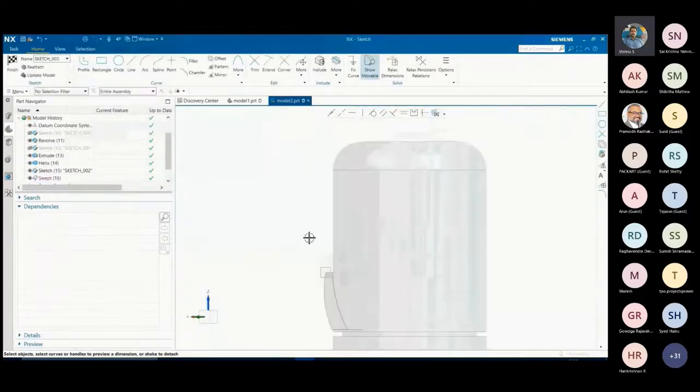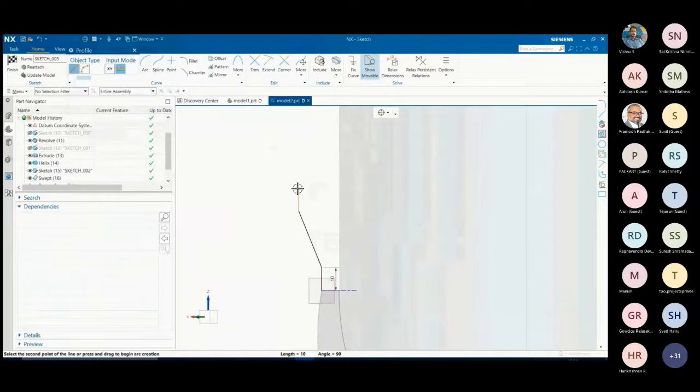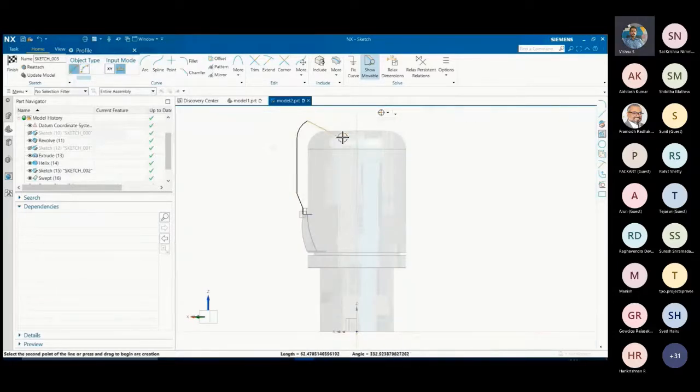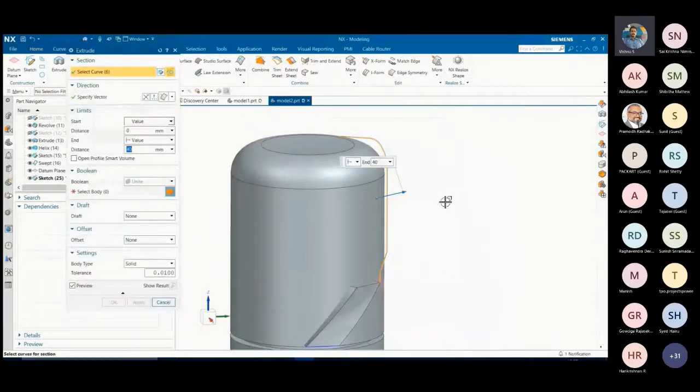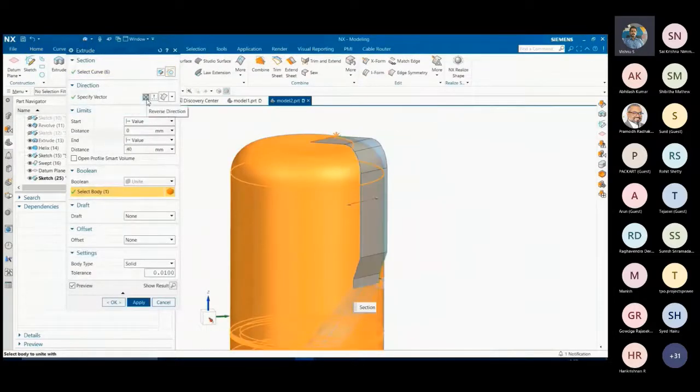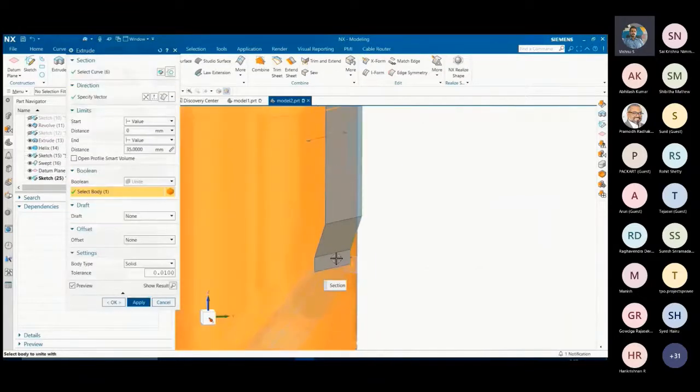So let's complete this helical vein by adding a profile. As you can see, it's a single chain that we are trying to make. Once that is done, we can use the extrude two-sided offset to basically add a surface and directly unite it with the existing body.